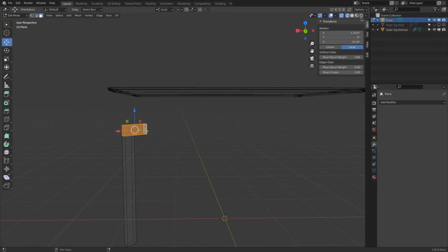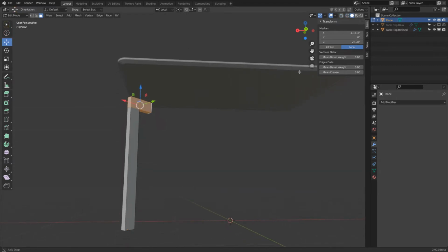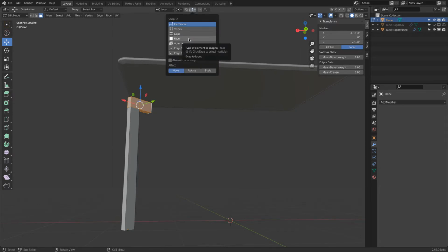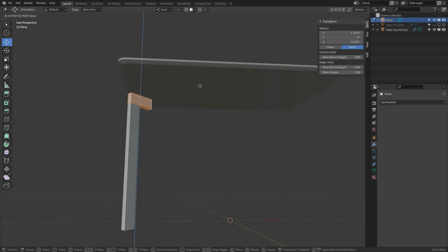Go to move. Go back to shaded view, and then here snapping. Honestly, the easiest one is to use face. So we snap it to the bottom face. Because these edges are rounded, I have more snapping targets. So more edges I could snap. And thus here with that face, I move this one up, hold control, it snaps to just that face.